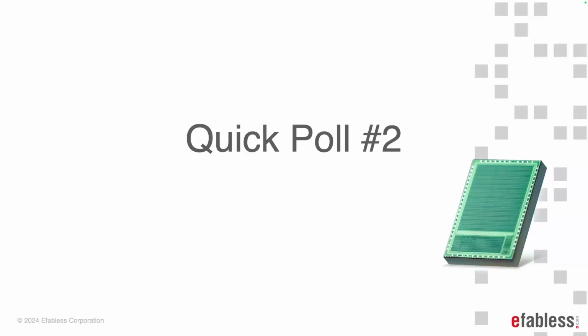Yep. In a 10 square millimeter ChipIgnite, it's on the order of 1 million gates. And the ChipIgnite Mini is about 1/4 of that, just under 1/4 of that. And then the SRAM size, David, do you have the commercial SRAM macro size off the top of your head? I think it's around 300 microns square, maybe a little off. Maybe a little bigger than that, but not by much. And number of bytes? That's a 4K, right? 4K. Okay. Yep. Bytes. Okay. Thank you for that, Tim.